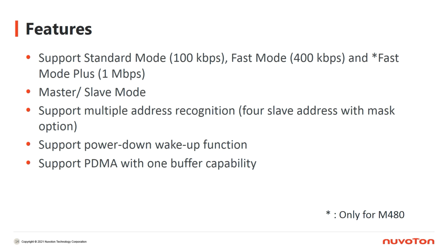I2C supports both master and slave mode. It also supports multiple address recognition. Besides, the I2C function supports waking up the CPU from power down mode. Also, we integrated with PDMA to provide faster data access capability.